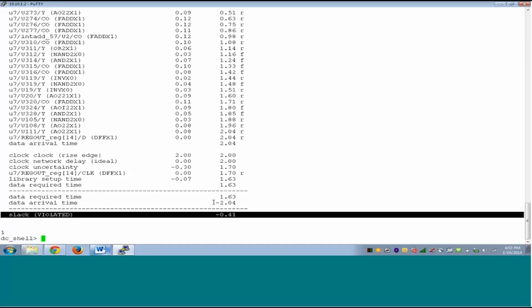What is timing critical usually is the register to register path. Now imagine an ALU of a CPU. A lot of arithmetic and logic operations go inside the ALU. Typically the core of the ALU, which does the arithmetic operation, would be timing critical, not the incoming ports to register or register to output. Now what is the problem?